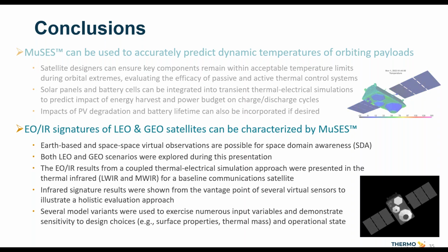And then moving beyond the thermal and electrical and looking at the signature side of things, we've explored both Earth-based and space-based engagement scenarios that you might be interested in for space domain awareness. We've explored LEO and GEO scenarios during this talk and shown how those can be simulated and the kind of interesting results that can come from those. We've shown how you can take the thermal results from a coupled thermal electrical simulation and then translate those over into remote sensor predictions in thermal infrared wave bands, mid-wave and long wave.